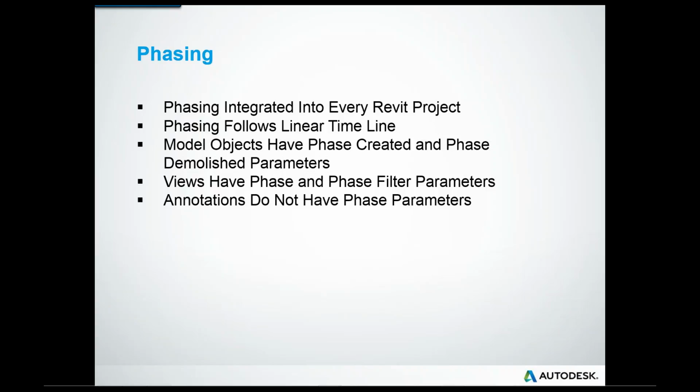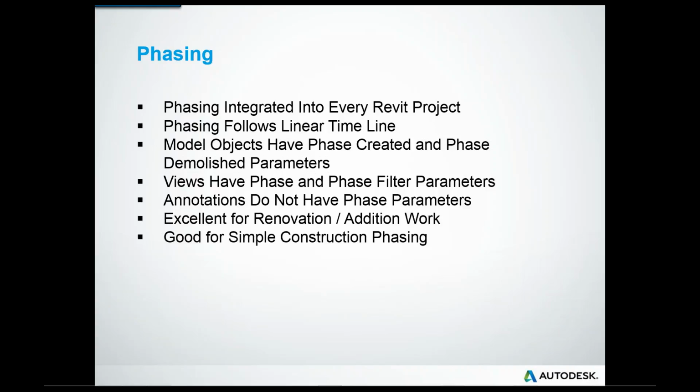This is kind of an advanced subject matter, but nonetheless, for those of you working in phases, your annotations are not subject to phasing. They kind of ignore it. And one of the things you can do is this is great for creating work that's in renovation or creating additional work. Basically, this is good for simple construction phasing.